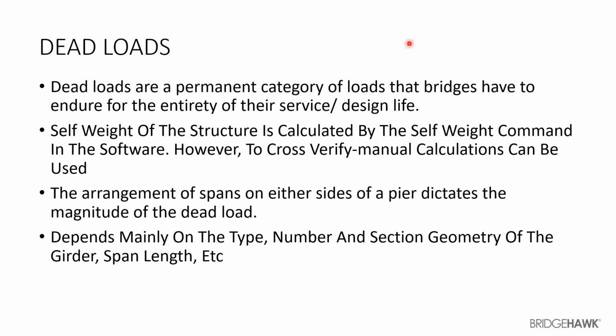If you make the manual calculation, it would serve you as a cross reference, because many times in the software we are very happy when we get a no-error file which runs smoothly and gives you a certain value. But you cannot be sure of that value unless you are backed by a manual calculation, which adds an additional security layer for you. So it is a very good practice to manually do the calculation and then go to the software.